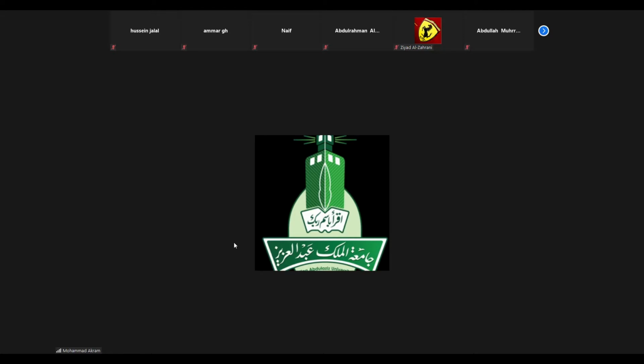If you read this, it is given: determine the rate of flow of water through a pipe of diameter 20 centimeter and length 50 meter, when one end of the pipe is connected to a tank and the other end of the pipe is open to the atmosphere. The pipe is horizontal and the height of water in the tank is 4 meter above the center of the pipe. Consider all minor losses and take f equal to 0.009 in the formula hf equals 4 f L V square over 2 g D.